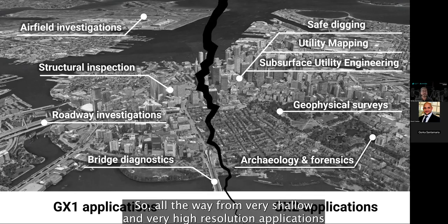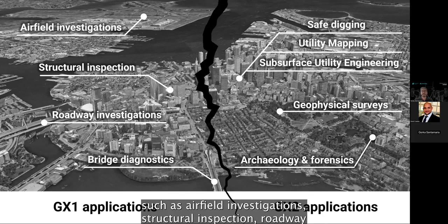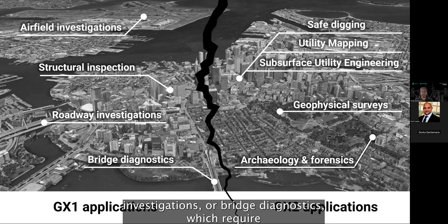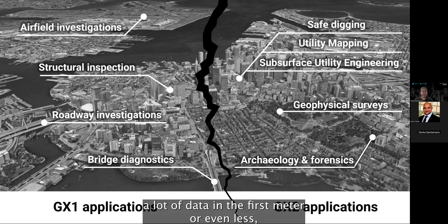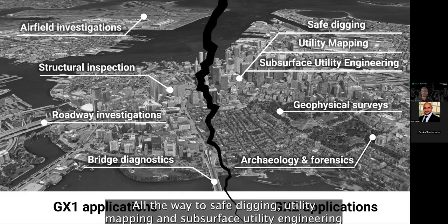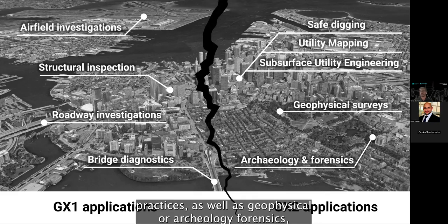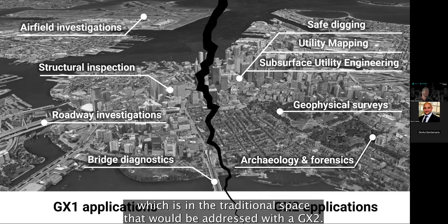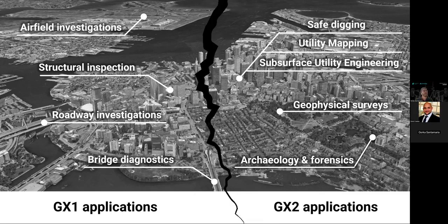So all the way from shallow and very high resolution applications such as airfield investigations, structural inspection, roadway investigations, or bridge diagnostics, which require a lot of data in the first meter or even less, and can be comfortably addressed with the GX1, all the way to safe digging, utility mapping, subsurface utility engineering practices, as well as geophysical or archaeology forensics, which is in the traditional space that would be addressed with a GX2.